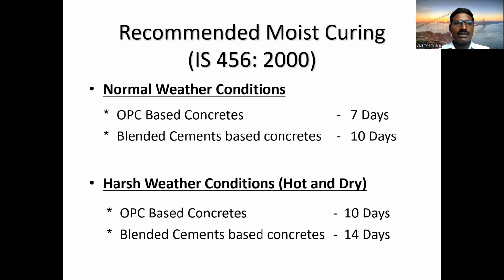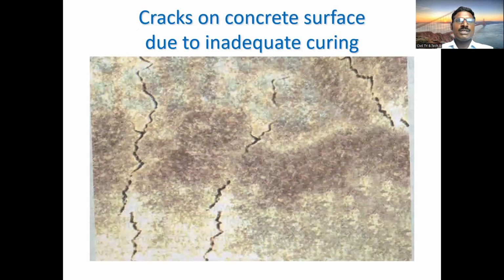The recommended curing for normal weather conditions is 7 days for OPC based concrete and 10 days for blended cement based concrete. For harsh weather conditions, hot or dry, we have to provide curing for 10 days, and for blended cement we have to use 14 days.